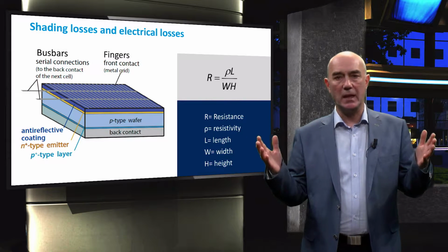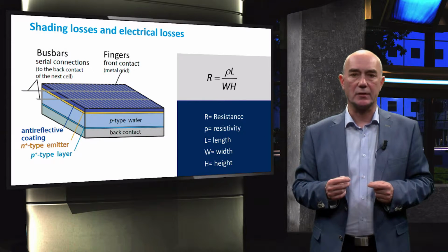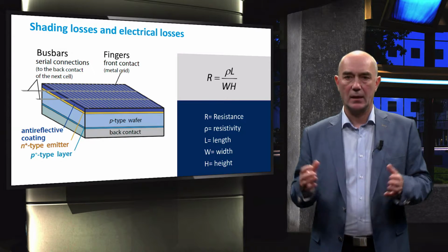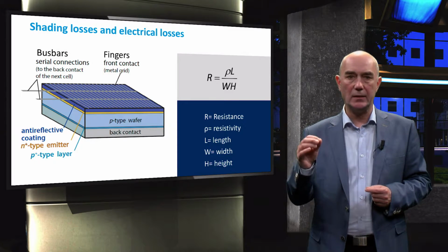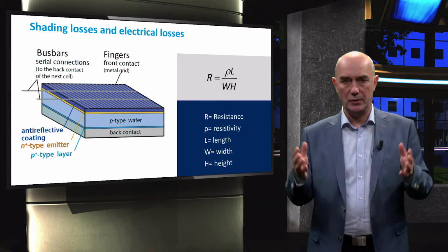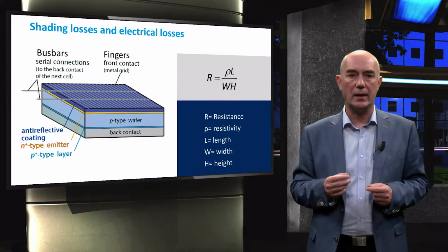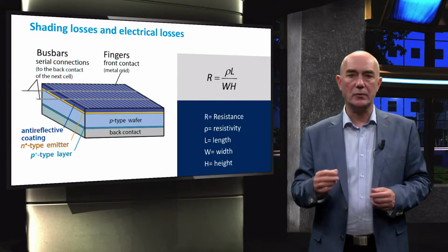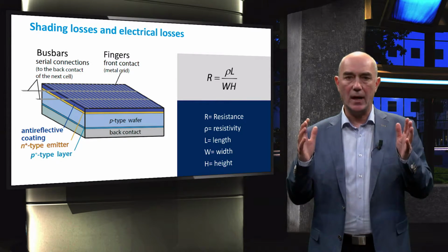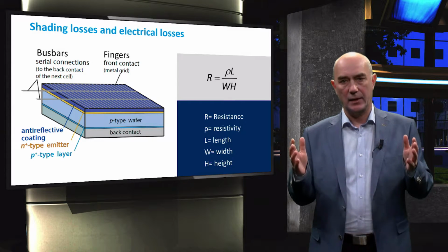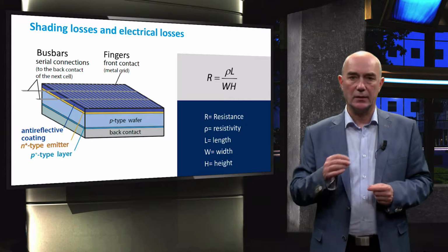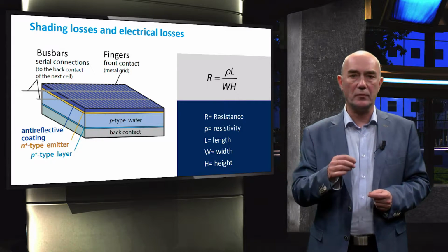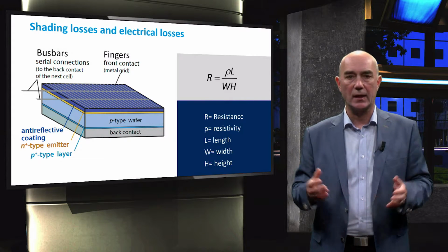This is a schematic figure of a standard silicon solar cell with an emphasis on the front metal electrode. The front metal pattern is made up of thicker bus bars used to make connections with adjacent cells and thinner fingers. This cell uses 2 bus bars and numerous fingers. As discussed in the previous section, the design of the bus bars and density of the fingers is a trade-off between the contact resistance and shading loss.